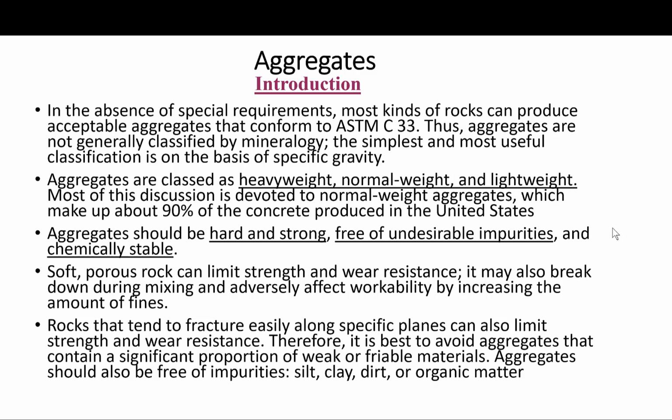Rocks that tend to fracture easily along specific planes, flaky stuff, can also limit strength and wear resistance. So it is best to avoid aggregates that contain a significant proportion of weak or friable materials, or at least to remove them. Aggregates should also be free of impurities such as silt, clay, dirt, or organic matter.